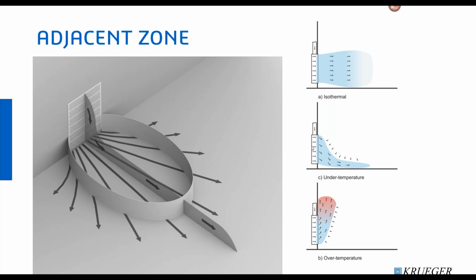However, in cooling, which is the main mode that the displacement operates under, you'll see that the cool air is cooler than the room air. There's a delta T, and so the cool air tends to fall towards the floor or spill out onto the floor.